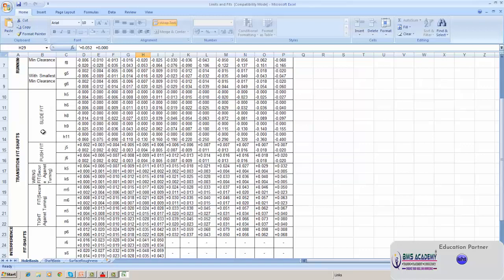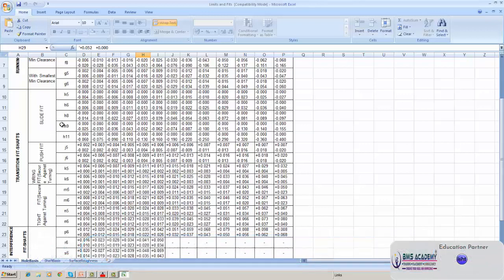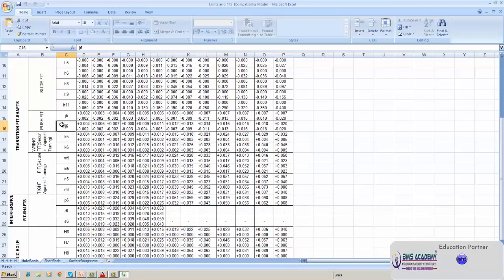For example, I took an example of a cylinder and a piston inside. It has to move inside. This is the tolerance of the diameter of the pistons. You can select it depending upon your design, and push fit in keys and all that. When you have a key on the shaft, it should be pushed to one side. It should go easily inside the gear, and the gear side slot should have a certain dimension, and the key width should be such that we should be able to push it to fit it.